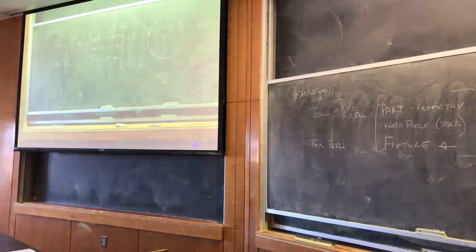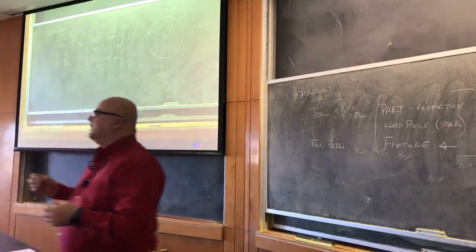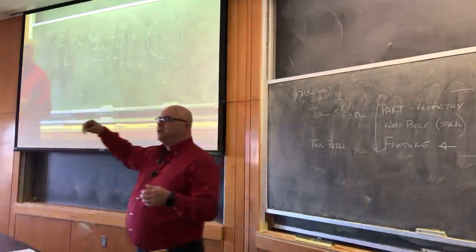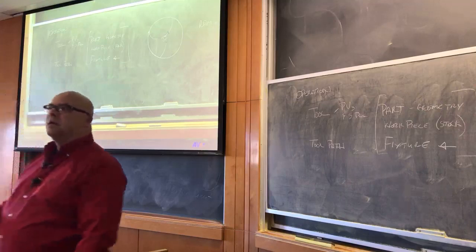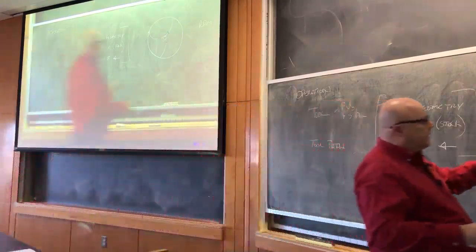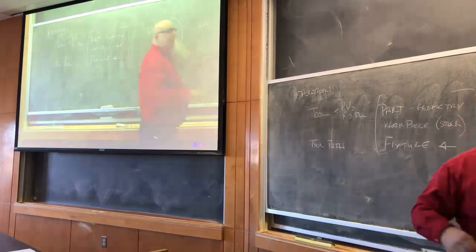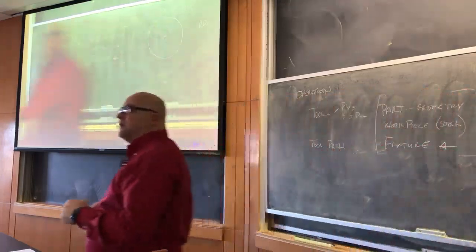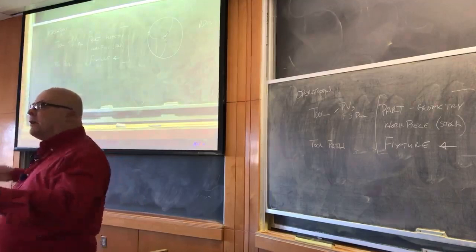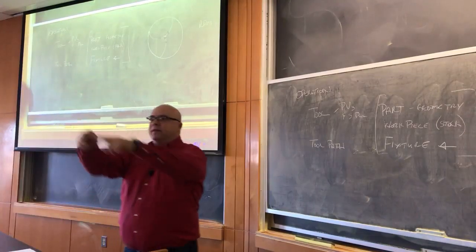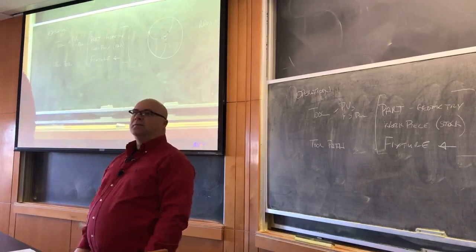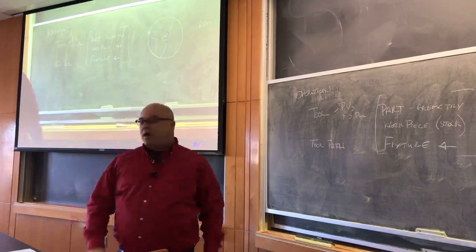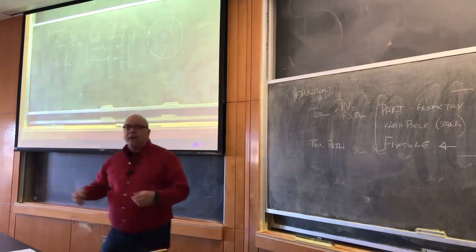You can come in at an angle. What's your name again? Molly. So Molly wants to come in at an angle. We call that ramping. So if you have the XY moving in a straight line and the Z moving in a straight line, that's a ramp into the part. If you do that, then you never actually have the center of the tool in contact with the workpiece. Now, what if you didn't have a long distance to go over for your ramp? Yes, you could do a helix. So we could ramp down a circle, right? So we have to consider how we are going to enter the part.